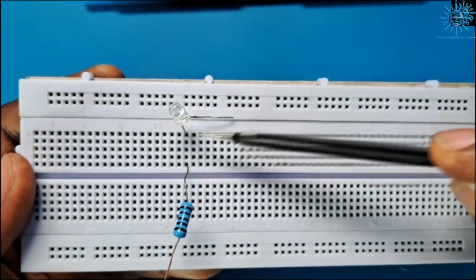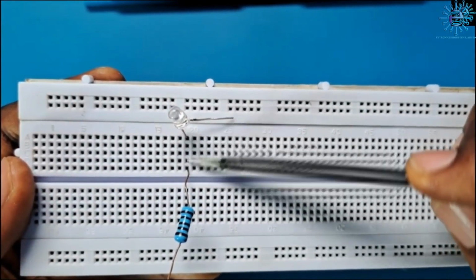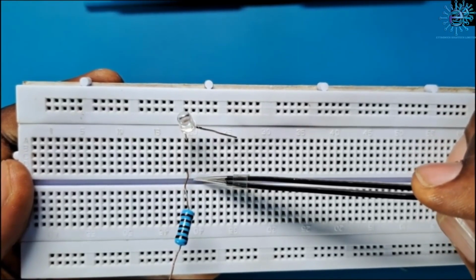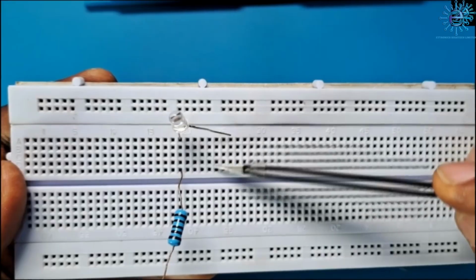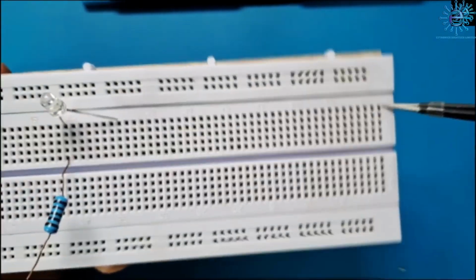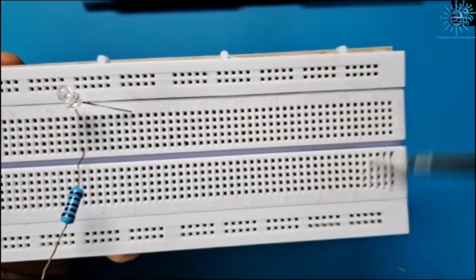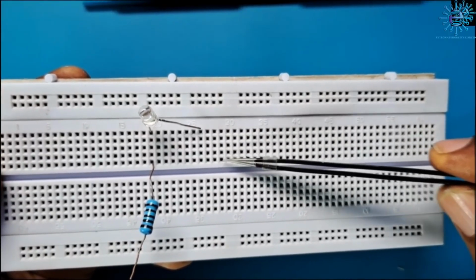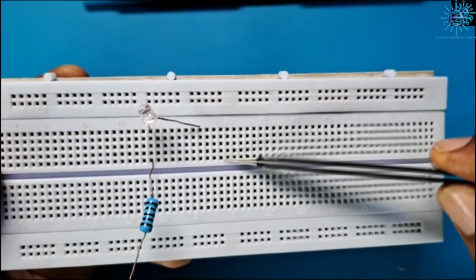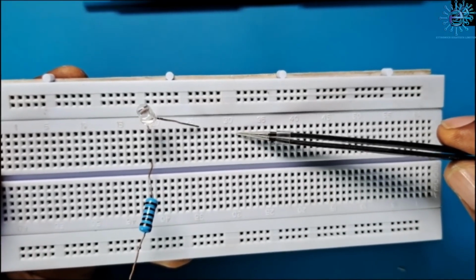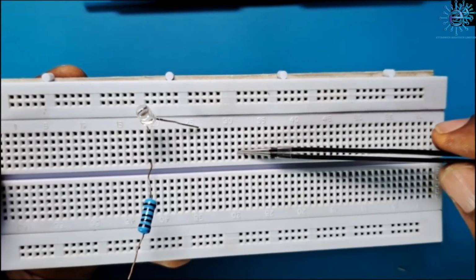So because we have continuity on this line, the two legs are now connected. I can do the same thing on this line, this line, this line, this line, up to this point. I can also do the same thing on these lines or on these lines. As long as you have continuity on any line, you can use it to connect the legs of your electronic components together without twisting the legs of the components.